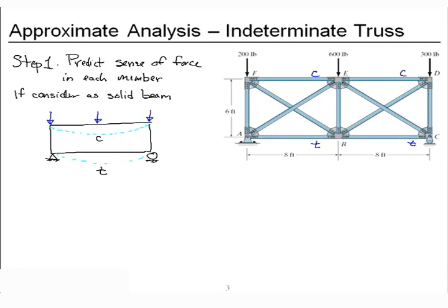All right, now let's take a free body diagram of joint C. Well, joint C is going to have a vertical reaction up, an unknown vertical force from member CD. It's going to have tension in member BC, which means it'll pull left at that point, and it'll have a diagonal force in member CE.